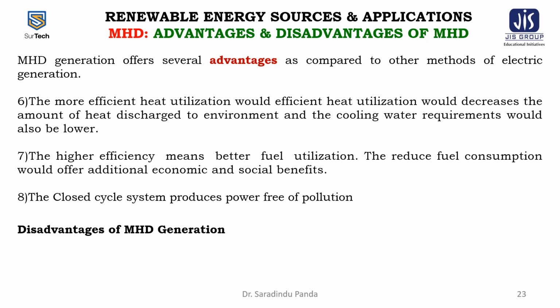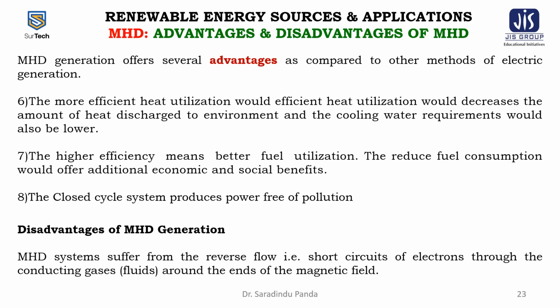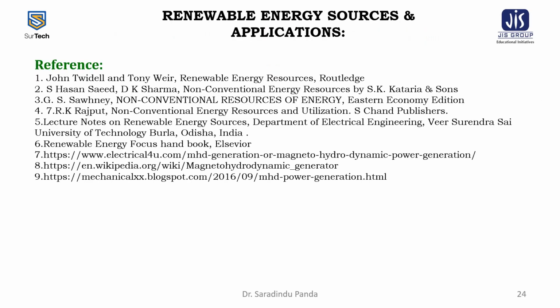Now come to the disadvantages of MHD generation. MHD systems suffer from reverse flow, such that there are short circuits of the electrons through the conducting gases around the ends of the magnetic field. This is the total discussion on magnetohydrodynamic power generation.